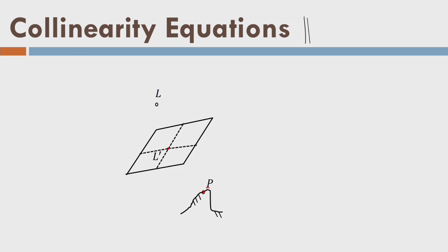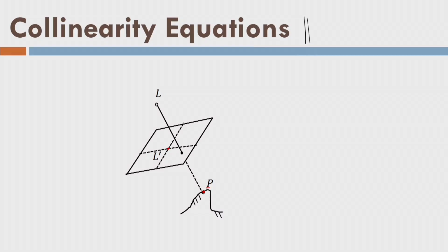So, assume that we have acquired an aerial image and we have corrected it for all the systematic errors and mathematical errors by transformation. So, I have an ideal image, that means it does not have any distortion. As a result there should be some kind of mathematical relationship I can develop. Let us see, this point is imaged at point p like this, as shown in the animation. This vector is Lp, from this point to this point. What about the other vector? I have another vector from point L to point P, this vector.